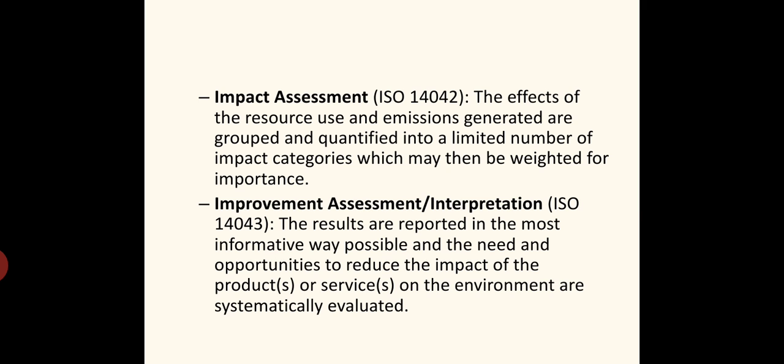And comes the impact assessment, ISO 14042. Now we have done the inventory analysis. Now how this product is going to make an impact on the environment is analyzed in this stage. The effects of the resources use and the emissions generated are grouped and quantified into a limited number of impact categories, which may then be weighted for importance. Some emissions identified during the inventory analysis may not be that serious compared to the environmental impacts. So that is categorized based on the importance.